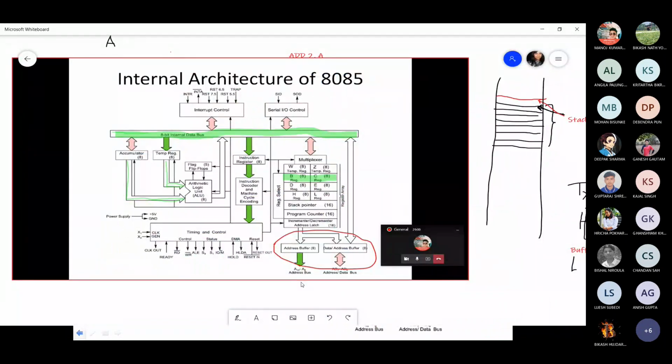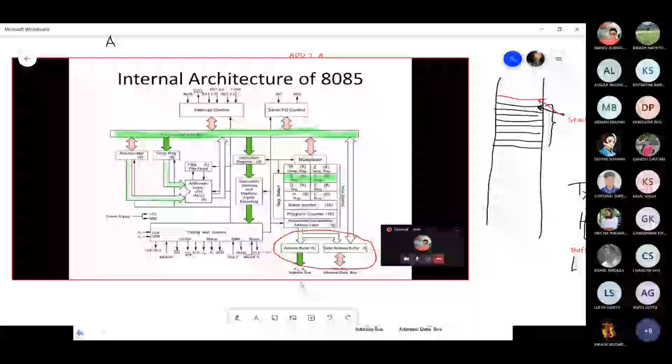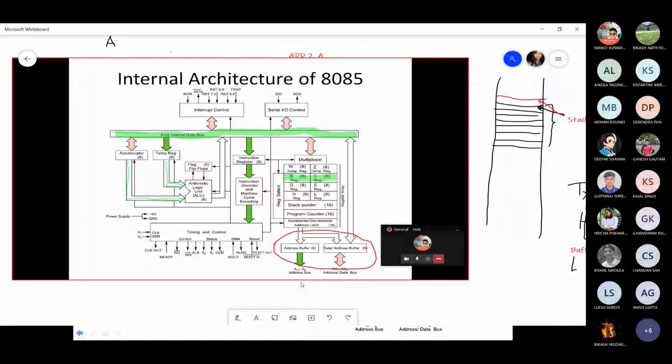So this is all about the registers in the register bank. We have the BCDEHL program visible registers, the WZ program invisible registers, the stack pointer to implement the stack, where the top of the stack is pointed, and the program counter, in which the address of the next instruction is contained. Okay, now out of the register bank we have a register called the instruction register.